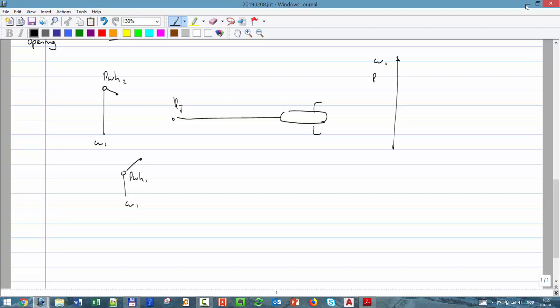Okay, we have wellhead pressure 1 versus Q1. It looks like that, right? And that's the sum of the IPR of well 1 and the sum of TPR of well 1. Okay, these are these two equations. I go from the reservoir to the bottom hole of well 1 and from the bottom hole up. Okay, and I impose the rate I want, this Q1. That's the rate I desire. And then I get some PWF.